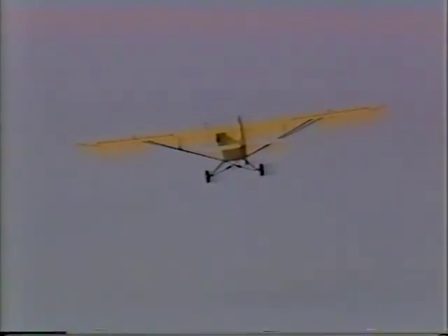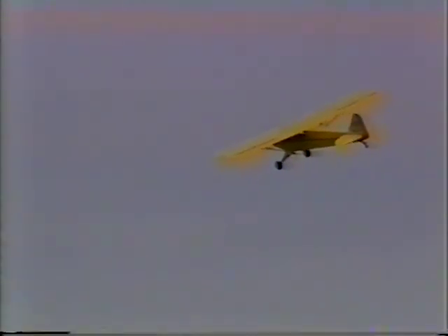Back in the days of the J3 Cub and so on, we had a USA 35 airfoil section on that. It was almost essentially a rectangular wing with just a little rounded wingtips on the thing. Had no twist to it, no stall strips, no spoilers, nothing else. And that airplane would be able to go to its maximum angle of attack, but when it stalled, it stalled rather violently and rather excessively, if you want to put it that way.